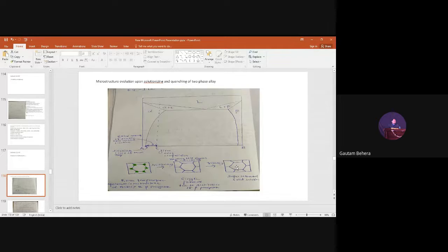Suppose I will take this material and I will allow the material to stay for, suppose, 5 days at a relatively low temperature, suppose 300 degrees centigrade, or suppose it is a steel, I am putting it at 500 degrees centigrade or 450 degrees centigrade. What will happen? Can anybody remember? If I allow the steel to remain for 5 days, 6 days, or for 2 days at 500 degrees centigrade. If this is steel and if this is an aluminium, suppose I am putting it at 250 degrees centigrade or 350 around. What will happen? Sir, high strength.